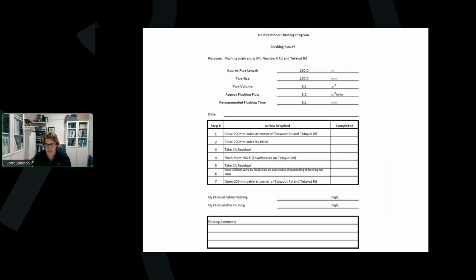We need you to put a pressure gauge here and measure the pressure at this point to make sure that it stays above 20 psi. I want you to close this valve at this corner and specify exactly which valve it is. You should also have, especially for your valves, directions on opening the valves afterwards, right?